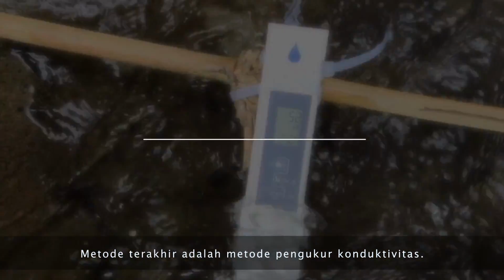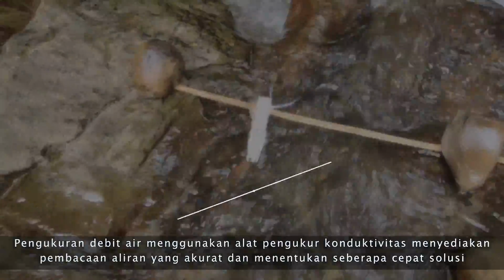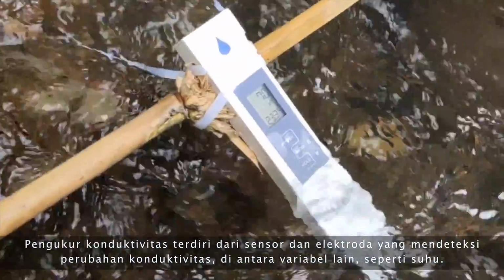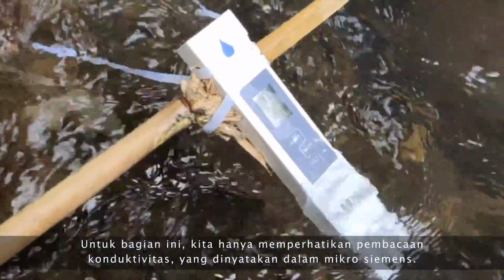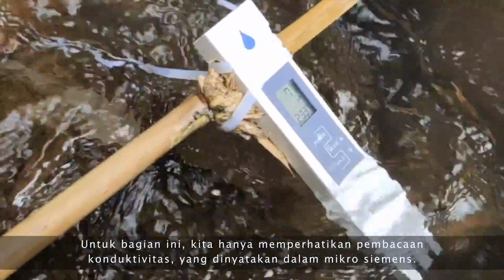Finally, the conductivity meter. Measuring flow using a conductivity meter enables an accurate flow reading by determining how quickly a premixed solution passes through your meter. Conductivity meters consist of electrodes and sensors that detect changes in conductivity, among other variables, like temperature. For this exercise, we are concerned only with the conductivity reading, expressed in microsiemens.